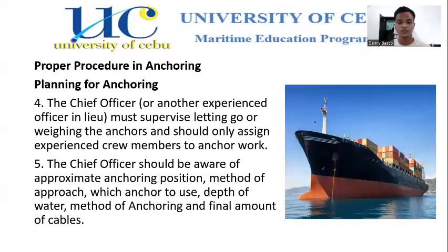Number four, the chief officer or another experienced officer in lieu must supervise letting go or weighing the anchors and should only assign experienced crew members to anchor work. The chief officer should be aware of the approximate anchoring position, method of approach, which anchor to use, depth of water, method of anchoring, and final amount of cable.